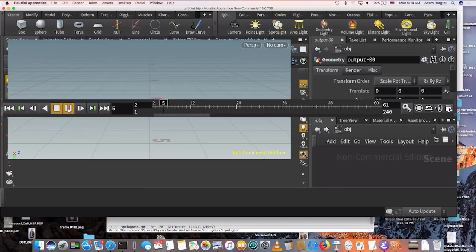Let me play this again. To the extent that you can see the faces that are showing up there, this is actually a volumetric mesh. I'm only rendering the visible faces. To the extent that you can see the scale of the faces there, those are the actual springs. So what I did was to take this object and run a meshing program on it and generate a volumetric tetrahedral mesh, and then for every edge in that tetrahedral mesh, we created a spring. If you were to create a finer spring network, you would get different behavior because you've changed your spatial discretization.